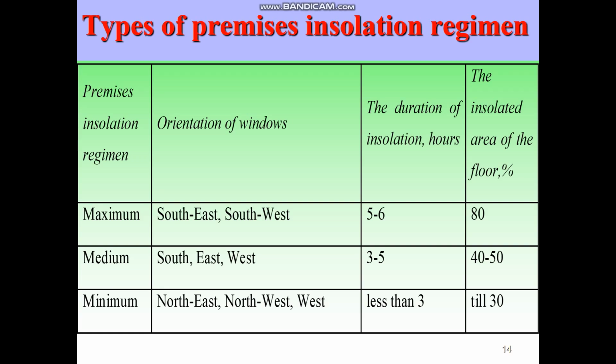Light energy acts on many physiological processes of the organism. In all premises assigned for long stay of people, lighting by direct and diffuse solar beams is necessary. Lighting should be intensive enough, uniform, matte, but not forming hard shadows.